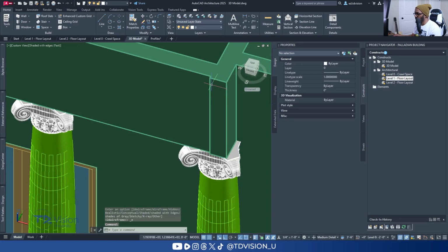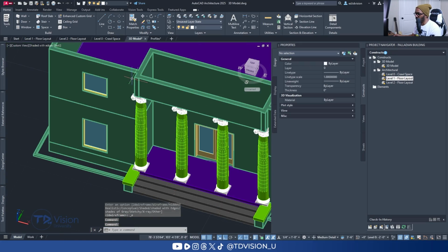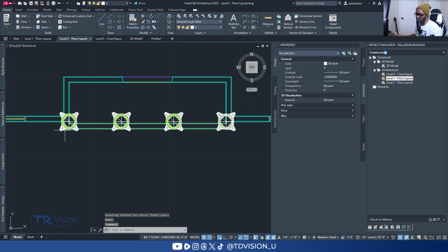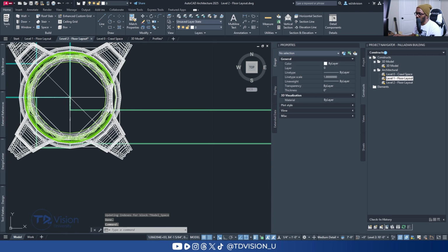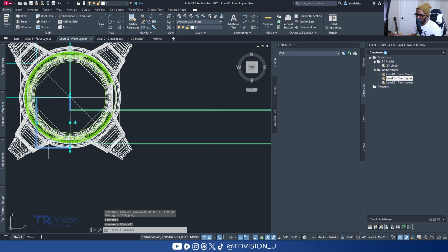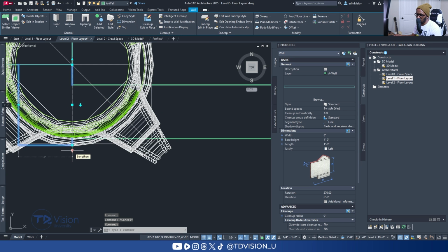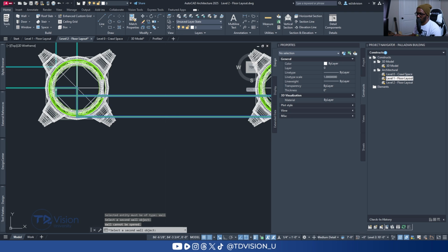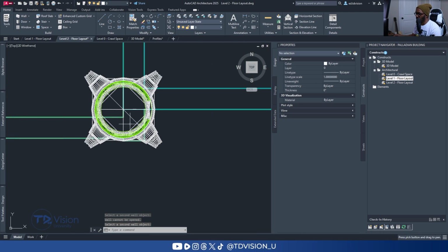Yeah, it seems like my wall is still protruding a little bit, so I still need to make some adjustments there. Let me see what's happening here with this wall. This wall here needs to be trimmed away. I think we could use the fillet tool, so let's do that. Click on this portion of the wall. There we go. And we'll do the same thing over here.